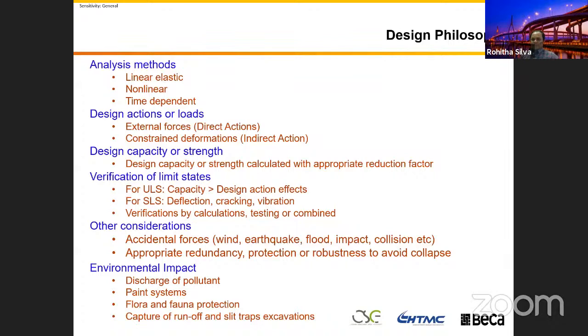For example, you perform calculation, you design your bridge, you get the dimensions of your concrete girder, and then your reinforcement content percentage, the pre-stress percentage, you detail everything, and it's based on your calculation. But when you say 40 MPa concrete, the cylinder strength of 40 MPa is closely equivalent to 50 MPa cube strength.